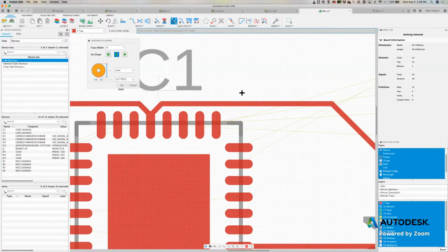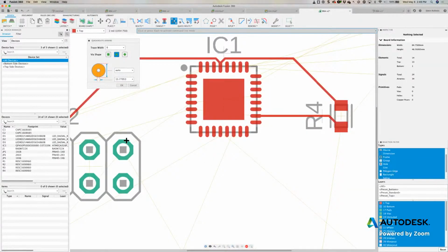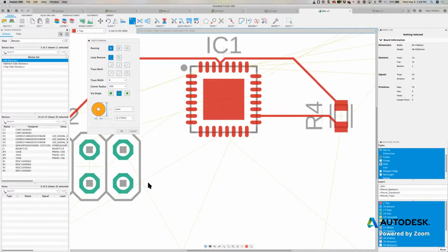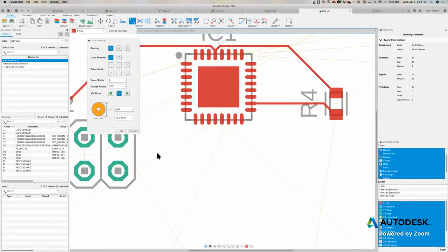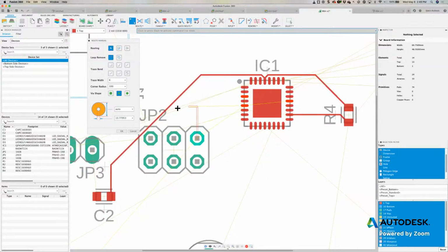So be very cautious about using anything like that. It does work though. There's just one more that I want to show you, and I'll do a quick route here because I thought it's very useful. I'm going to undo this and do a manual route, because I want to show you this feature. I've used it in combination with the auto router in the past. So let's say I'm routing this line that I have here. I use the route mouse key to use the opposite bend style.